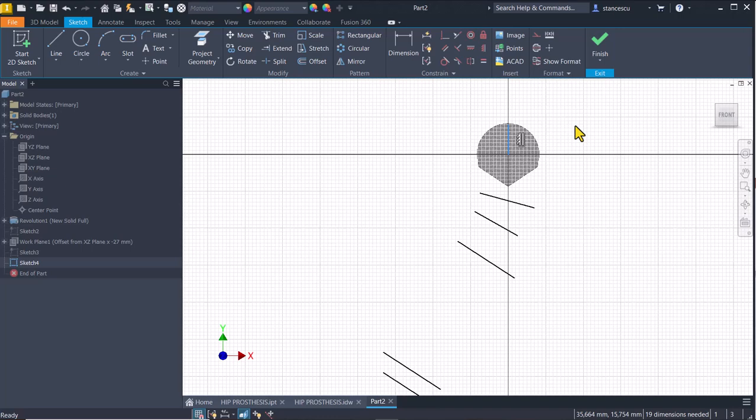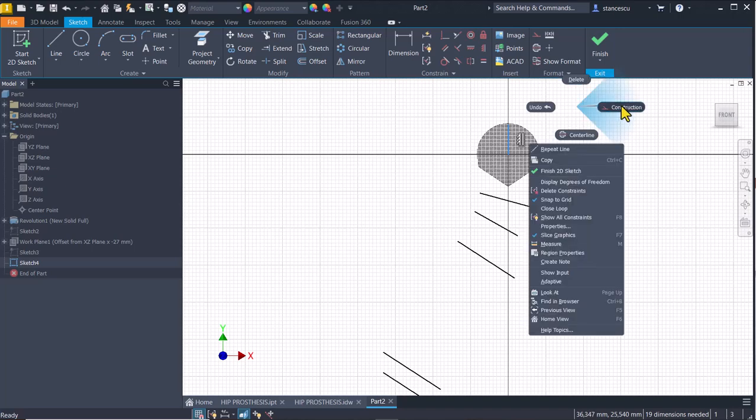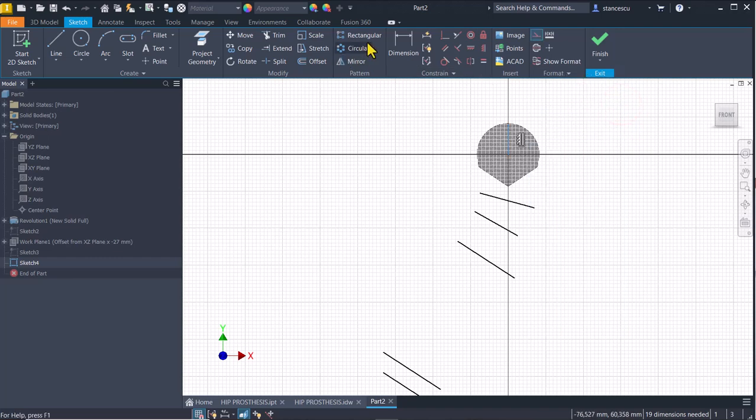and I'll use another solution. I don't click here, but right click and construction. It's simpler. I place on this line the center point of the first line. That point is placed at 38.5 from up. 38.5.